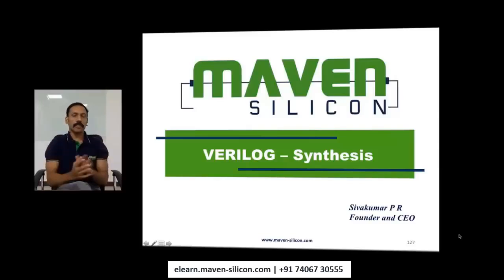There are EDA companies like Mentor, Synopsys, and Cadence, and they have different tools. There may be variation in the synthesizable subset, but you have to find a common subset. Whatever source code you have written should work fine with any kind of tool. That's called tool-independent source code.